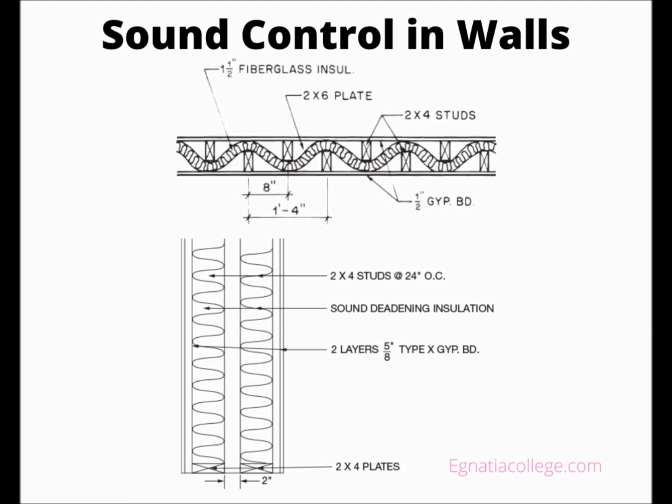The STC rating of a wall can be improved greatly by not allowing the studs to contact both surfaces. This may be accomplished in one of two ways. One method is to attach clips made for sound insulation to the studs and then fasten the wallboard to these clips. The clips absorb the vibrations. Using the clips and sound deadening fiberboard results in an STC rating of 52.